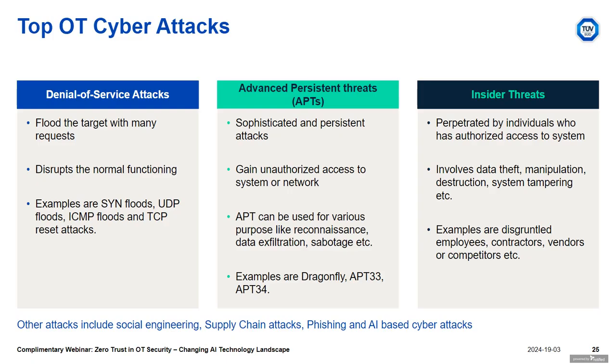Exploiting vulnerabilities in ICS systems. It is a software-based system, and in the past it was not developed with a secure development lifecycle mindset. Those vulnerabilities will be exploited, and that's why secure by design becomes very important in avoiding these attacks, as part of the mitigation strategy. You can provide multi-factor authentication to leverage security, or anomaly detection solutions in OT to cover it. But the crux is that if the software was built with security from the initial stage, definitely some of these attacks will be avoided.